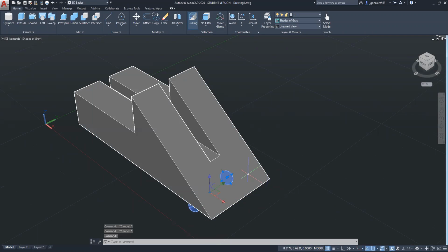So now that I have a cylinder, radius 0.25 going through the face, I took advantage of the coordinate system on the face. So it's kind of like when you're doing the iso circles with the left plane or right plane on the last homework. So this becomes the plane I'm working on because I have my mouse on it. The difference is the other one you have to choose the plane, which makes it a little harder. But now that we're in 3D, it's not as bad.